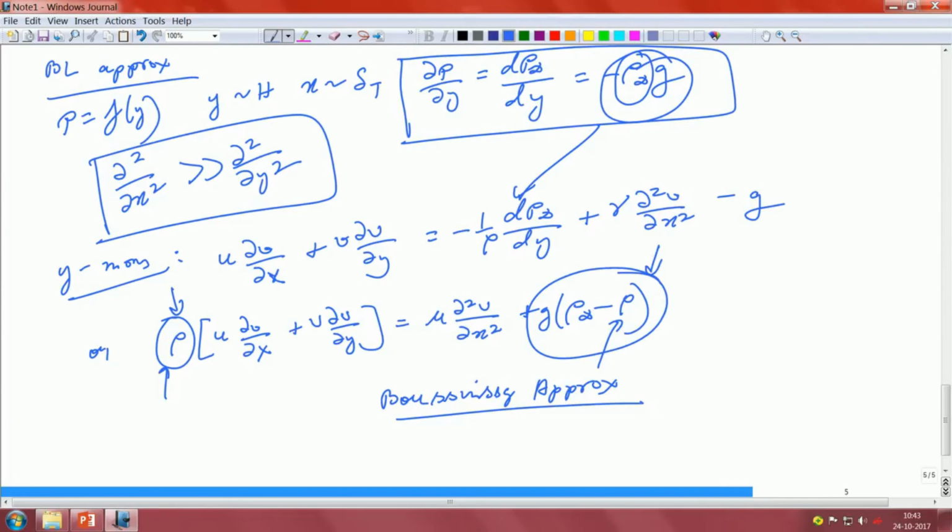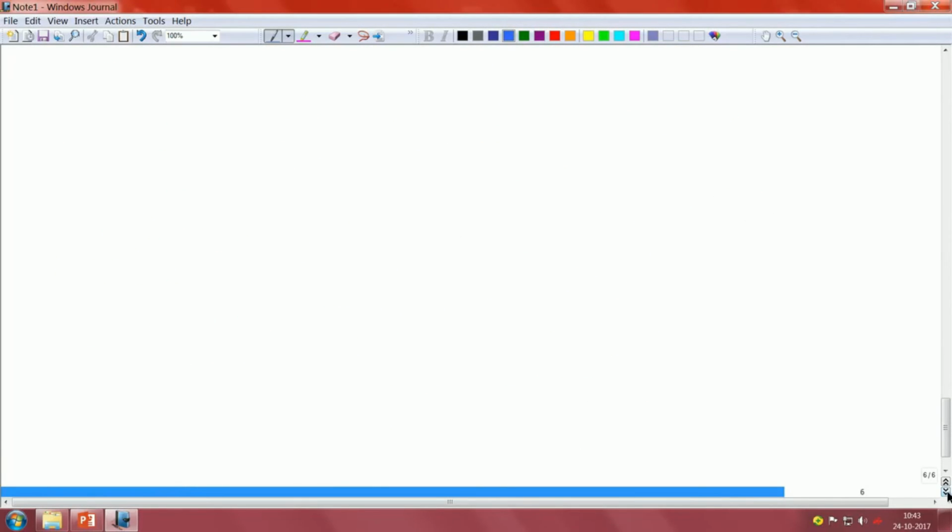Point number 2 is that the density on the right hand side, let us now express that density in terms of temperature. So, you see that we are differentiating the problem, we are stating that this is still an incompressible type of a problem. That means, most part of the Navier-Stokes equation is actually behaving with the constant density term. However, in the body force term, when density is present, we are taking its variation into consideration. So, that is the thing that Boussinesq approximately did.